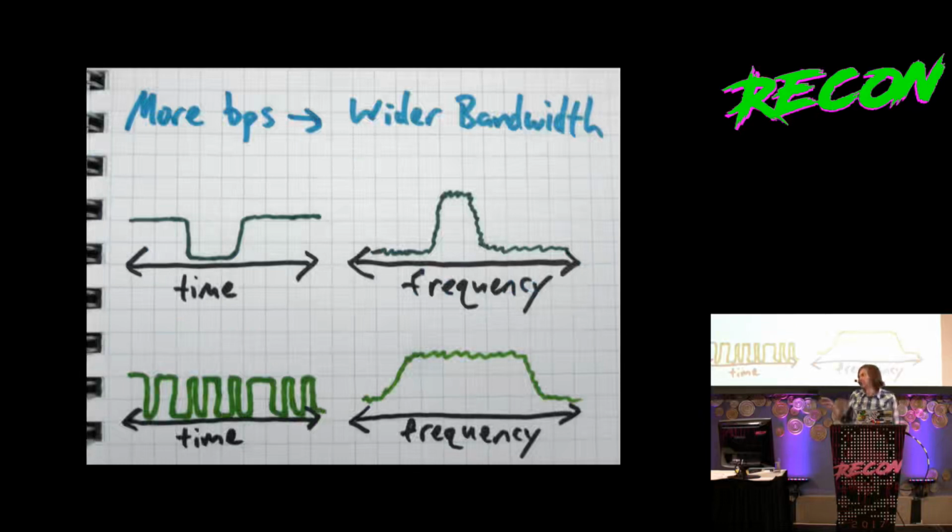In the upper left-hand graph, I'm showing maybe a sequence of a 1 and then a 0 and then a 1 and another 1. If you transmit some bits using any old modulation, that signal will use some amount of RF bandwidth, some width in hertz over the air.